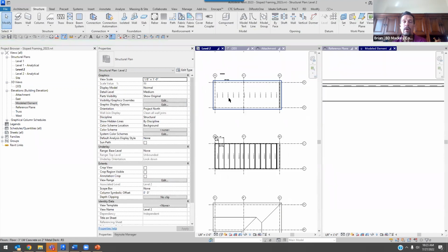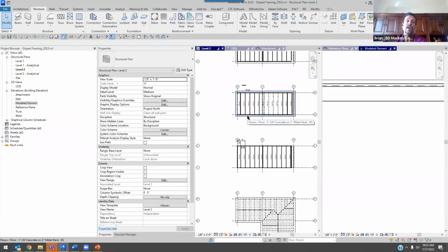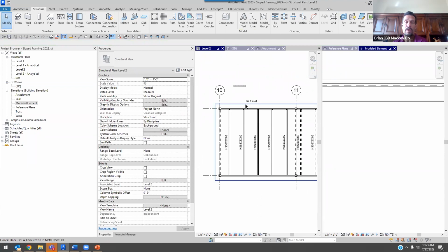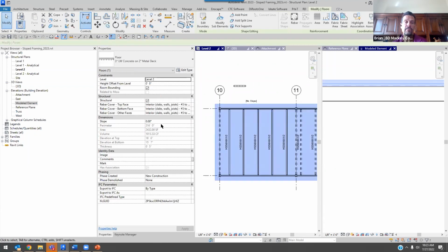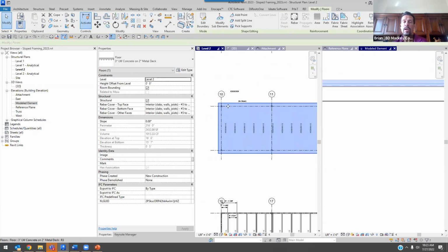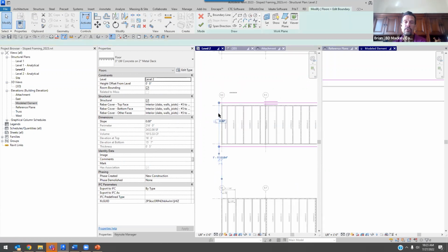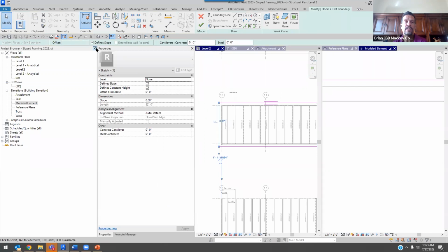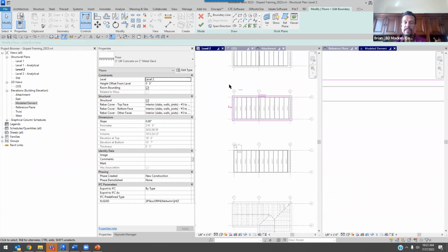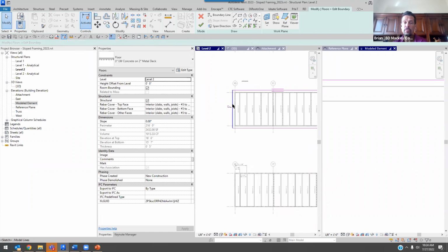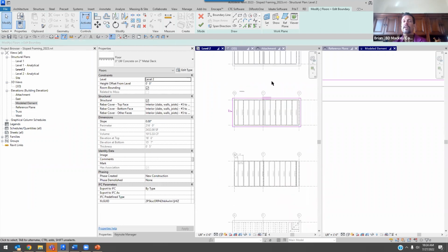Cool. Now, one advantage of doing it on the underneath side of a deck like this is now I can just grab this roof and define the slope, right? When I modeled this floor, I'm going to say edit boundary. I did choose one of my sketch lines and say, hey, it's going to define the slope. So in my floor, this is where the slope is being controlled from. I said, give me one of these as a sketch slope.